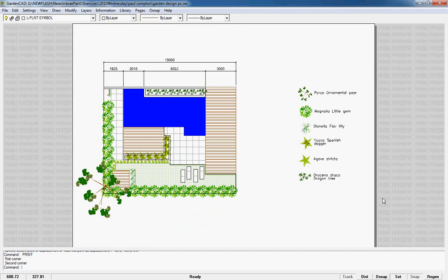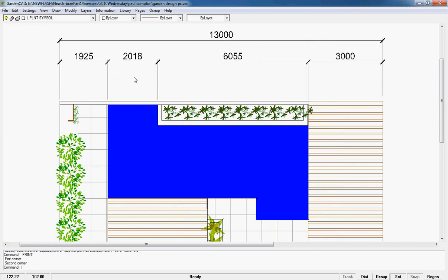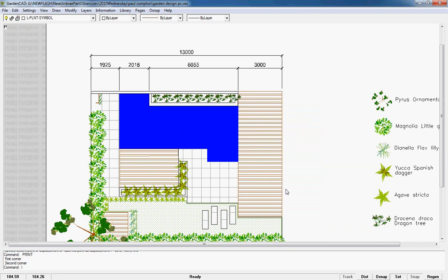So we could in fact put a scale rule on there and scale from here if we'd been very careful about our plotter and accuracy of our plotter and so on. But the value of putting the dimensions on here, you can put a note down the bottom that just says, do not scale off this drawing. The dimensions written on the sheet take precedence over everything else, and your construction team need to verify those numbers on site. So it's very dangerous to scale off the drawing, but we can legitimately plot or write down the bottom here in our title block area, A2 sheet, scale 1-to-50.